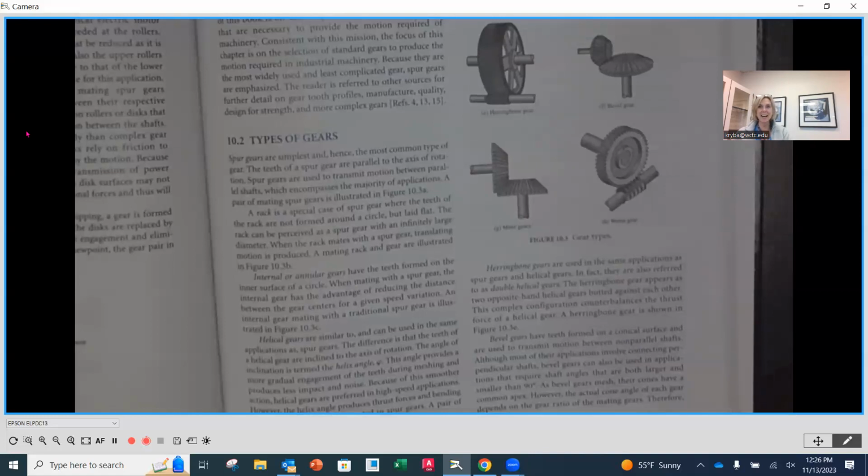Applications that I have specified actually use them specifically on servo motor applications, where you do have things that are going back and forth, because they have what we call zero backlash. We'll talk about backlash in a little bit. It's really just a gap between when you change directions. So I found it interesting that they said they're not normally changing directions, but in many applications, especially servos, you put worm gears on the end because they are a lot more accurate and provide zero backlash.